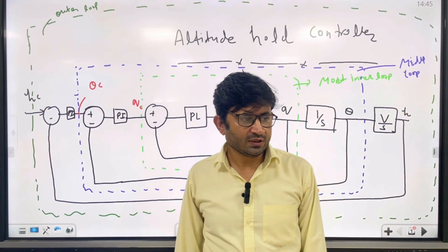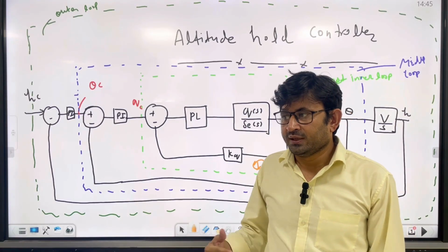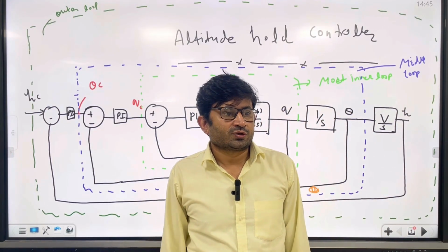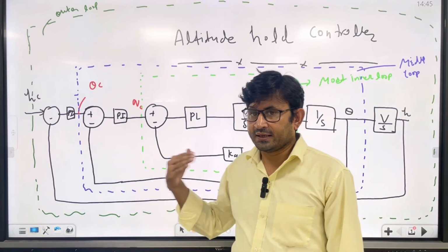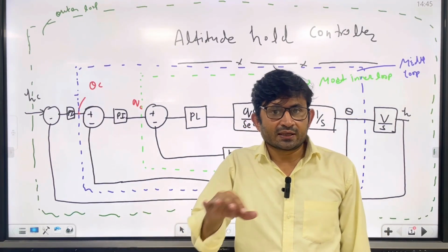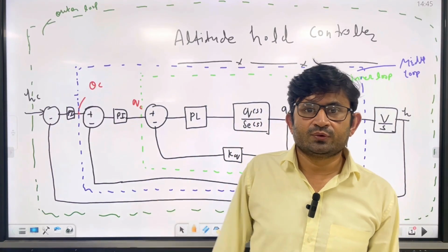Okay. So that means as a flight computer, when you take the data from the gyroscope, accelerometer and all, the most inner loop, the rate loop, will run at a higher frequency, and then the angle loop will be a little slower, and then finally position will be the slowest loop.